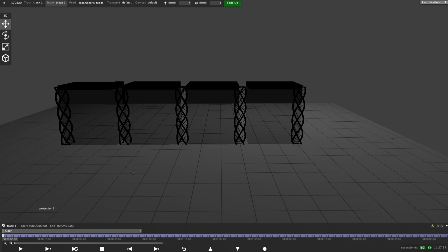So now we can actually turn these into a screen right now. So let's add some media. Earlier I grabbed some Beeple content. This is Glass Vein by Beeple, but I'm going to change my mapping type here, and I'm going to do a parallel mapping. And the screens I want it to see will be my lift screens. So now I can adjust the size of this to lock to my aspect ratio. I'm going to bring it out. And I'm also going to position it up a little bit, so we're kind of in the middle of the field.